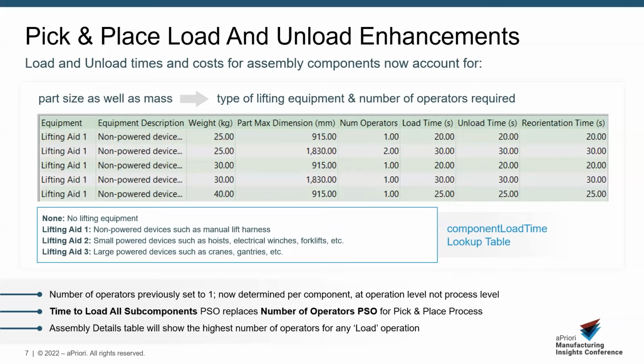And this also shows where we make the distinction between something which can be loaded by hand versus something which will require a lifting aid, which is always about 15 kilograms or 35 pounds, based on the recommendations given by most countries' health and safety or OSHA type agencies.